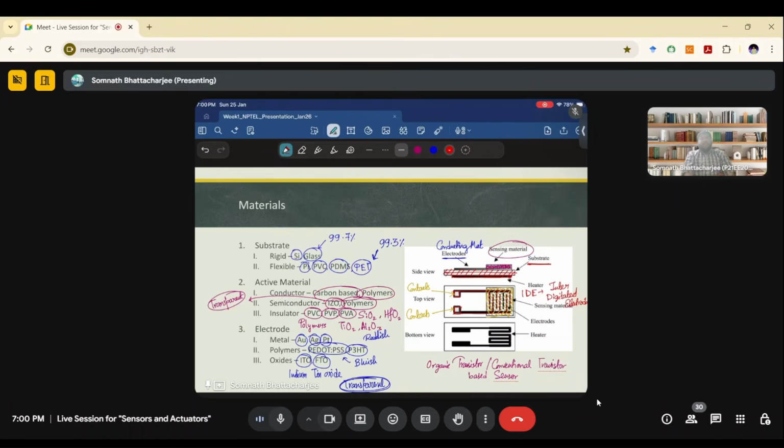Let's say these transparent materials are not very durable under very high temperatures. So you need to set the limit of these sensors as well. So let's say these materials or a few of the functional layers are getting destroyed after, let's say, 150 degrees. So if your use case is, let's say, you need to measure up to 130 or 140 degrees centigrade, you can use this sensor in that case. So in your use case it can be useful. But if I am measuring, let's say, 180 degrees centigrade, it may not be useful for my use case. And in my use case, let's say I don't need it to be transparent, so I'll use different materials and a different technique as well.